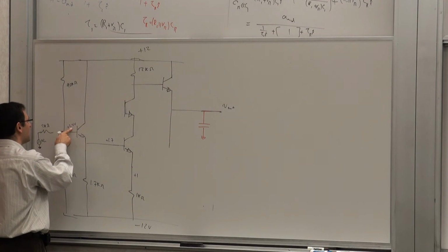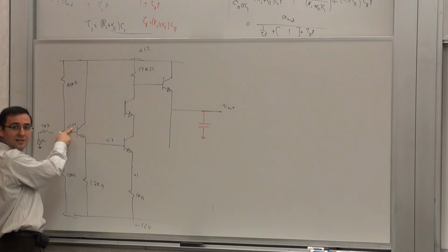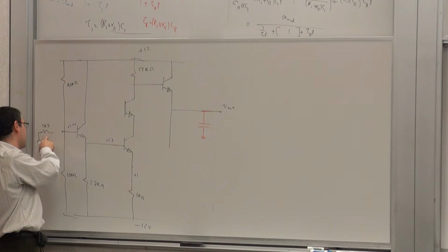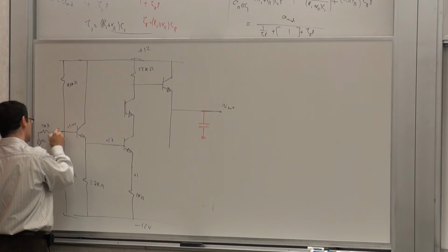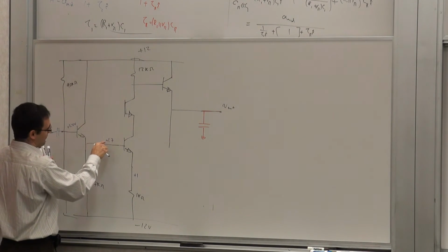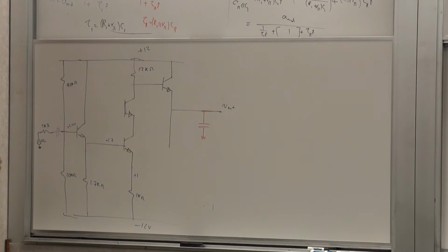But this voltage, remember, what is this voltage at? Absolute, it's like minus 9.6. So I can't connect it directly here. So I have to put some sort of a capacitor. A lot of times, if I want to make it more interesting, I can put a capacitor between here, bias to 10. I'm not done with biasing though.